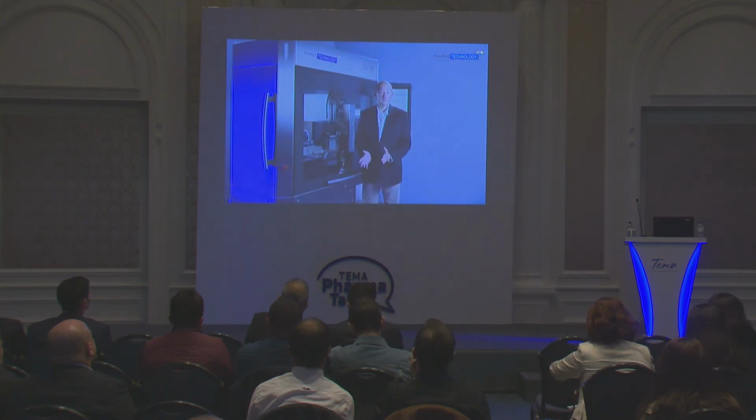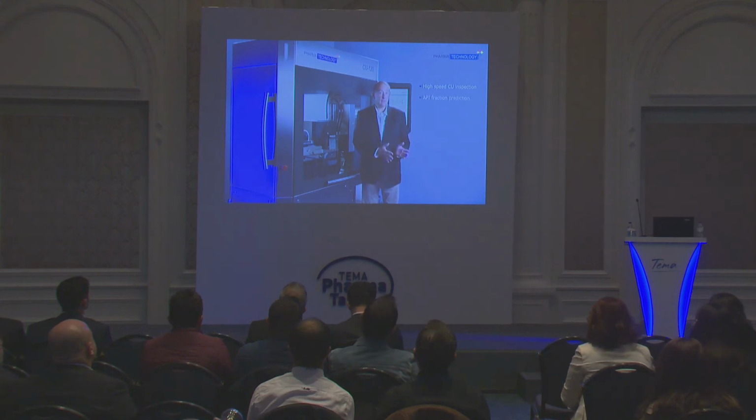This brand new system is a world premiere in the industry for high-speed Content Uniformity Inspection. It measures individual API fractions and mass of each single tablet up to 120,000 per hour. The machine has 3 inspection technologies on board, arranged along one single line. A 3D laser scanner gives us the tablet thickness and diameter.